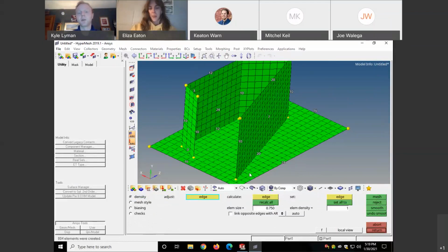Now, typically for something this size, I would actually go with a small mesh. You want it to be tighter, you want more elements, it gives you more detail. Kind of think of it like, right? A 4K computer screen gives you lots of detail. It tells you information without as much pixelation. But here you can see this is like a 360p TV. It's not very detailed. Your analysis isn't going to be very accurate.